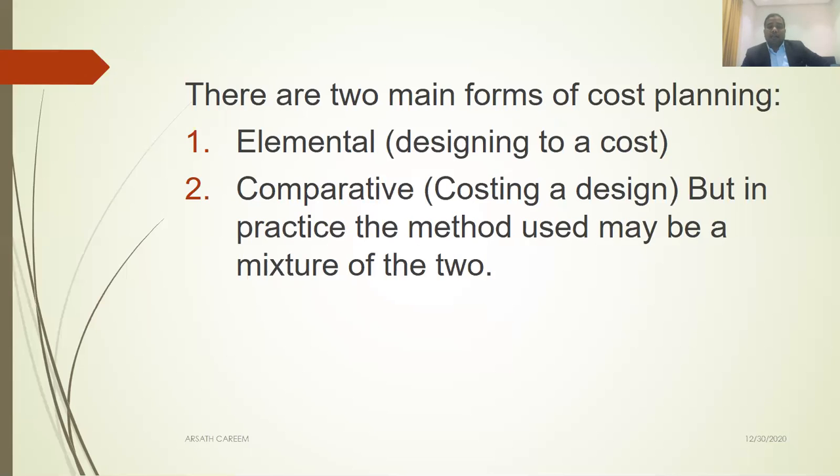As a quantity surveyor, when you prepare an elemental cost plan, you give it to the architect. The architect's target, his aim, should be the maximum budget that you provided. For example, the same scenario we took before, a 100 million hospital project, we allocated substructure 15%, so 15 million. That is the cost for the architect.